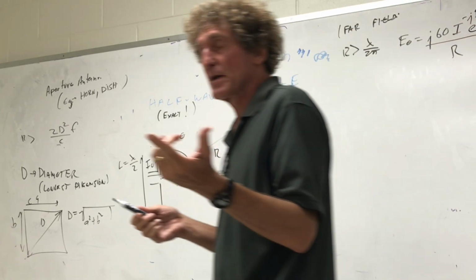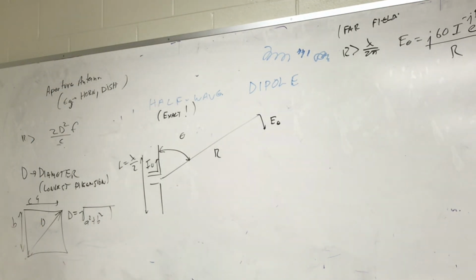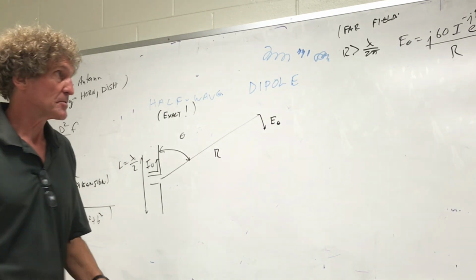In the real world, if you're working in a field measurements lab and you do this kind of stuff, a lot of people are just technicians. It doesn't always make sense to them, and they forget that. Straight wire antennas are different. So just remember that, all right? At least somewhere in the back of the mind, if you're in an anechoic chamber, figure out if you're in the far field and default to that kind of a measurement, because it's almost always aperture antennas.